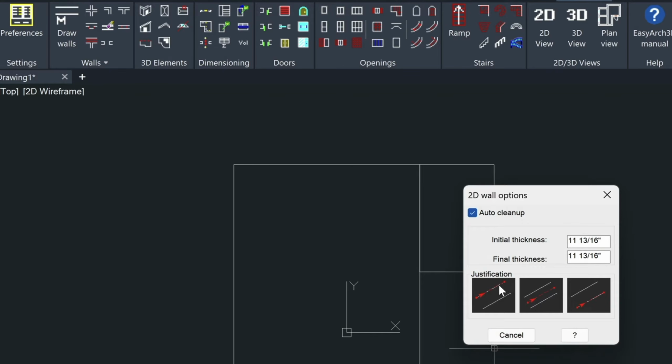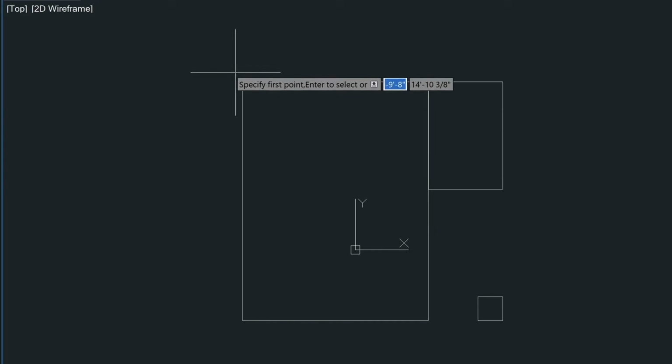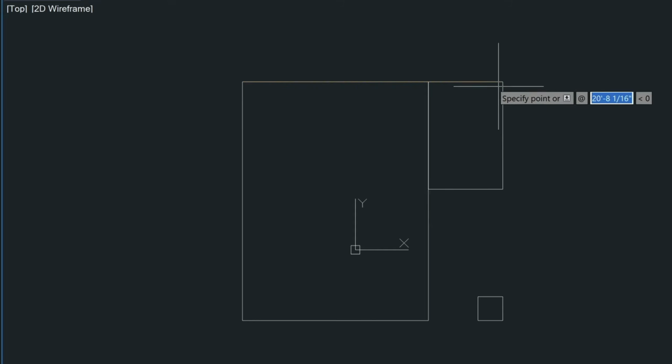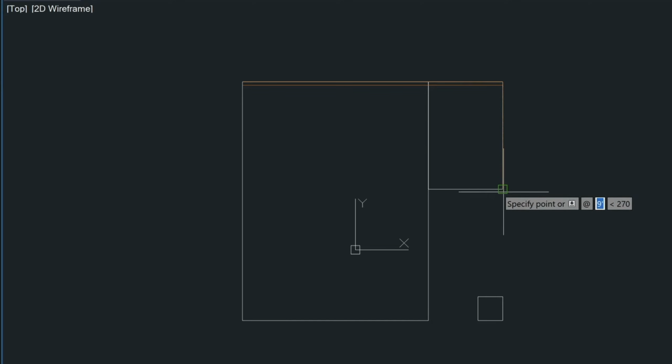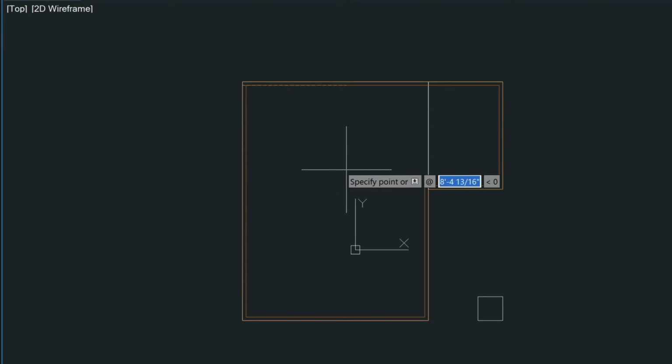And so now it's really just a matter of clicking this and drawing the walls. This is the outside wall here. So we'll just choose this. We need to specify our wall width. We'll make it 3.5 inches. And we'll click this, and then we'll just start tracing our outline of our building here, and press enter.